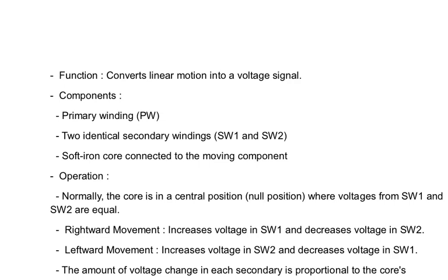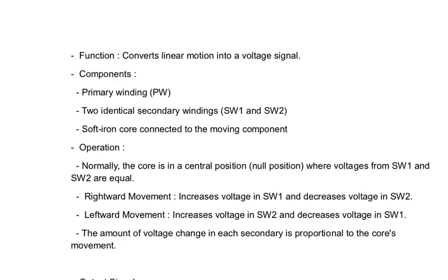As I had said, this core is movable. When you move it rightward, the voltage in SW1 will increase and SW2 will decrease. When it is moved leftward, the voltage in SW2 will increase and SW1 will decrease. So this is the actual working of it.